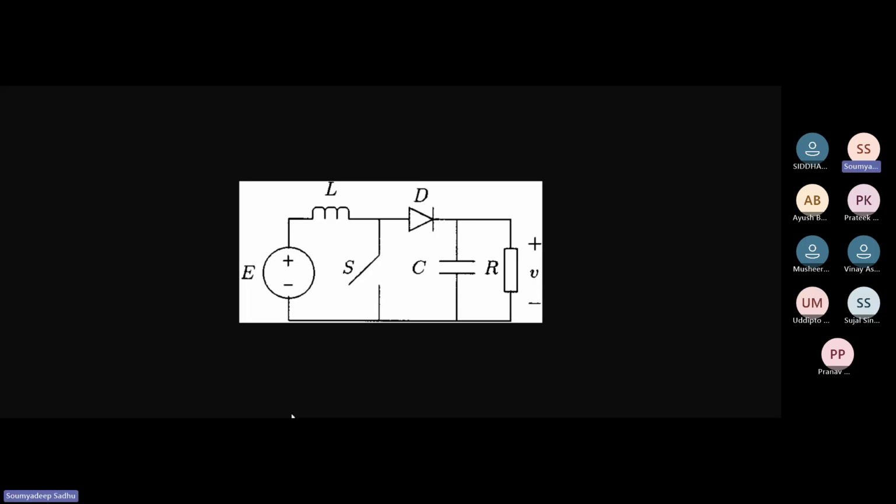If the duty ratio is 3.3 by 5, that may give the right output on average, but with a clock duration of 1 second, the MCU will be turned on for 3.3 by 5 of the period and then turned off. That is turning the MCU on and off each second, which doesn't make any sense.